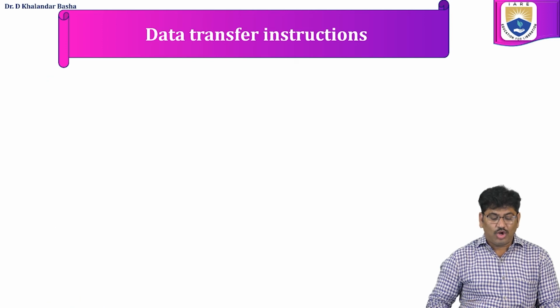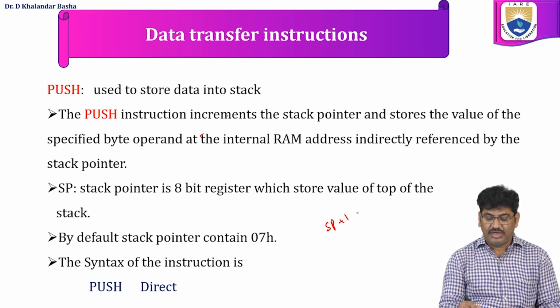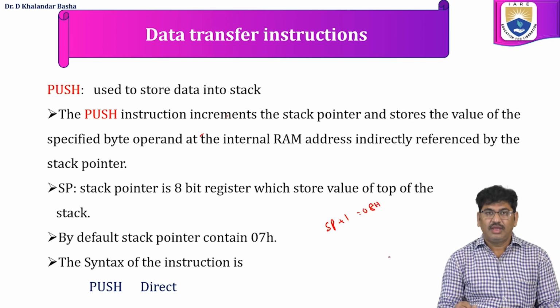For every push operation, first the stack pointer is incremented by 1. So that is 08H. Onto the memory location whose address is 08H, the data will be pushed.